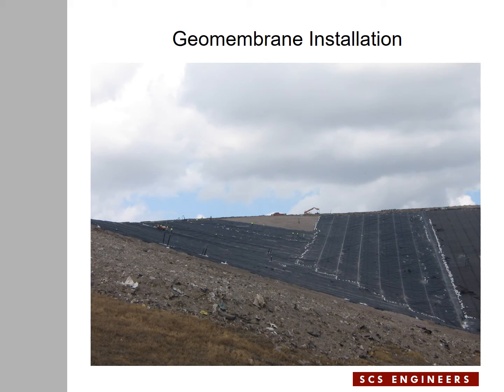As parts of the concave surface are already covered with geomembrane, only one small area near the top remains to be covered. So it's the superintendent of the installation crew who decides how to deploy the geomembrane panels in order to come together. The installation of geomembrane panels is not as significant for the discussions related to the geocomposite and the issues with the concave surfaces. The next step, the installation of geocomposite, is the important part.